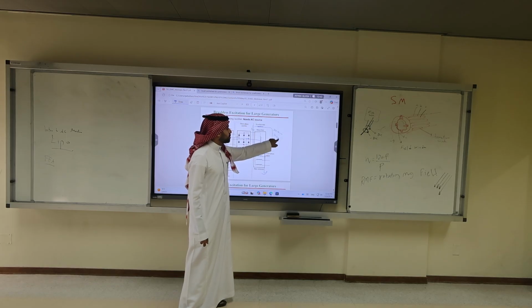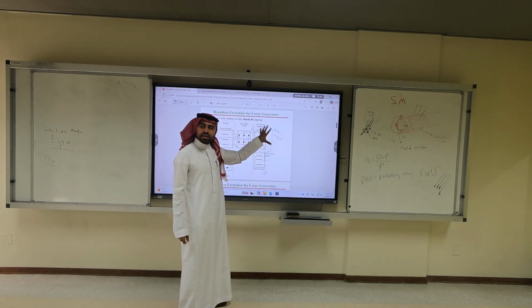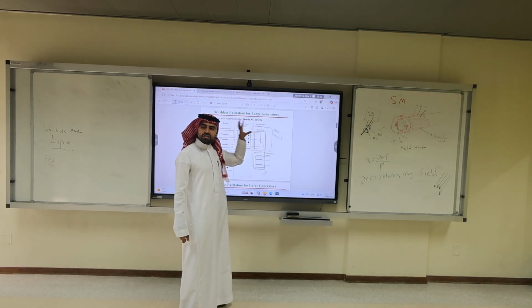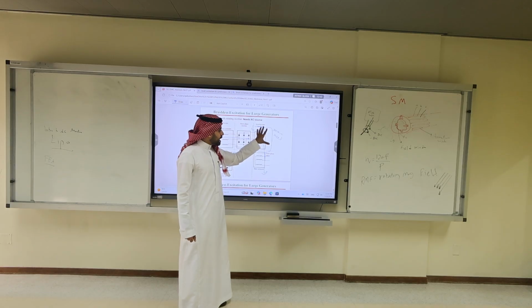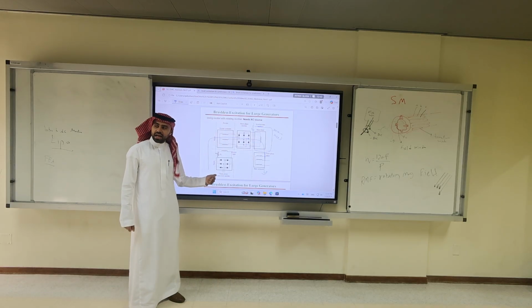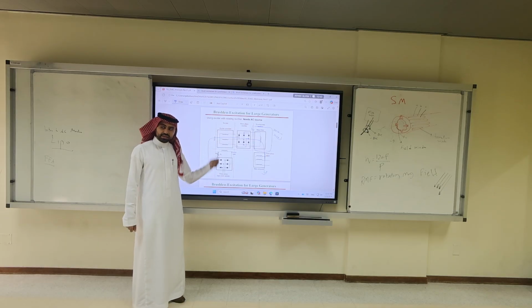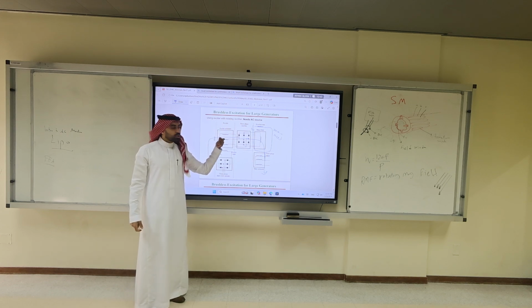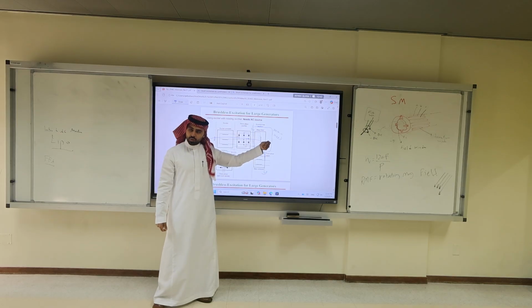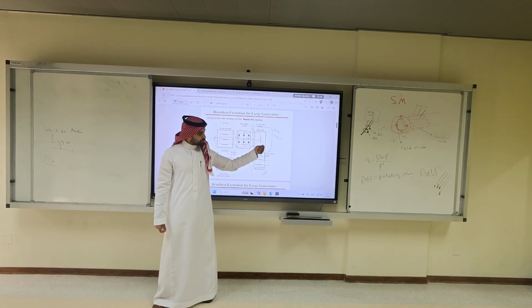The main need is we need to have a DC current flowing in the majority of the rotor windings. To get that, you need to have a small AC on the stator, rotate the rotor. Stator is always fixed. You induce on the rotor an AC, but this AC is small. You rectify it, you get what? Small DC. You need small DC. Small enough. Then you get the three-phase out.